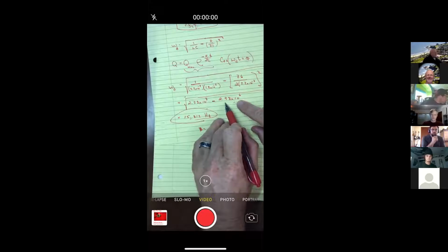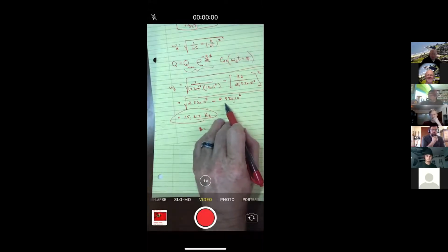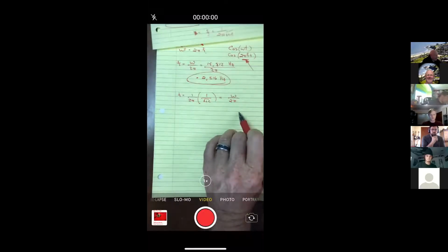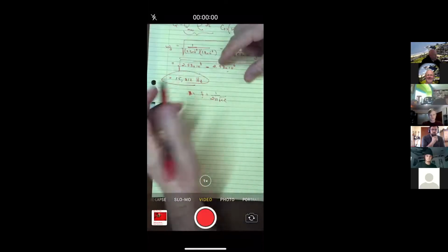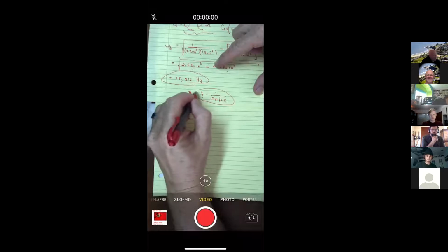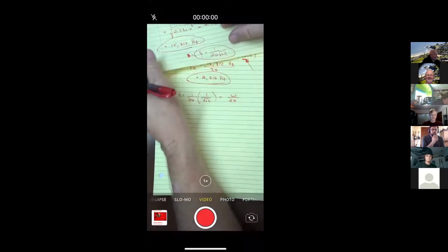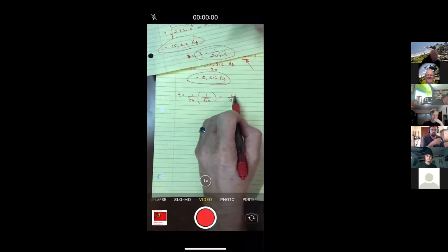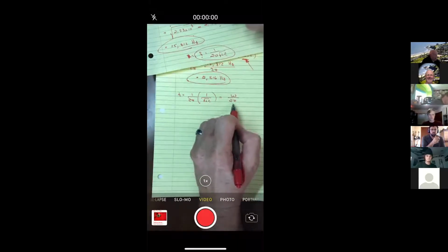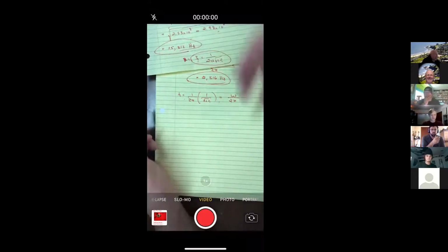If this was a circuit that didn't have a resistor in it, then the equation you read to me would be the appropriate combination of two steps. Number one, getting the angular frequency, and number two, dividing it by 2 pi to get the linear frequency.